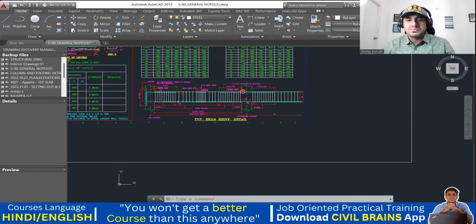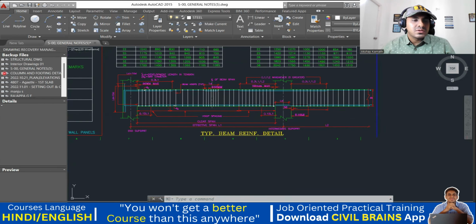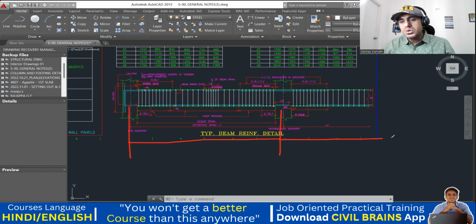We have two spans. One is this span, from here to here, we have one span. And then here to here, let us say there is another span. It's a two span beam. So let us say this is 6 meter and this is 7 meter. Out of 6 and 7, which is higher? 7 meter. So whichever is higher, you will take. That means for 0.3 into 7, I'll do.